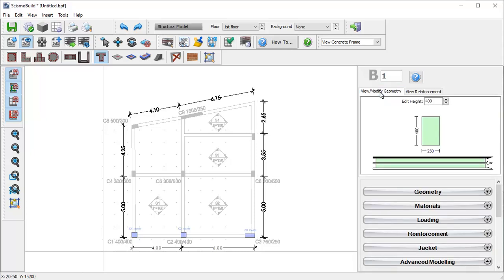We should notice that there are 3 parallel lines along the beam length on the beam section drawing. We must choose one of them as the insertion line along which the beam will be inserted in the floor plan. In our case, the top line is chosen, and for this reason, it is highlighted in black color. Here, we will choose the bottom insertion line.